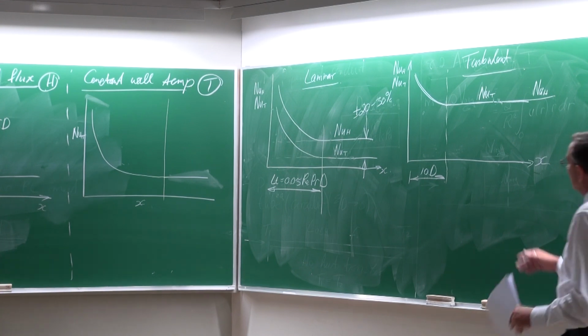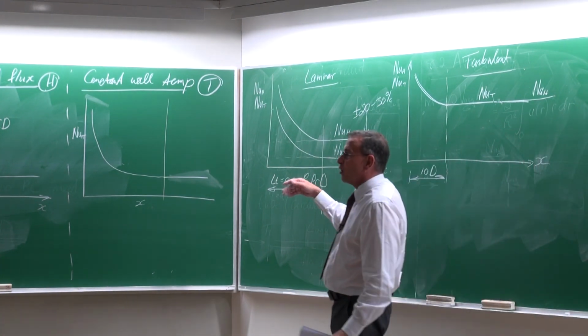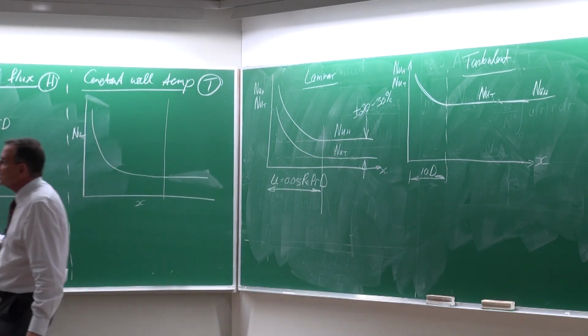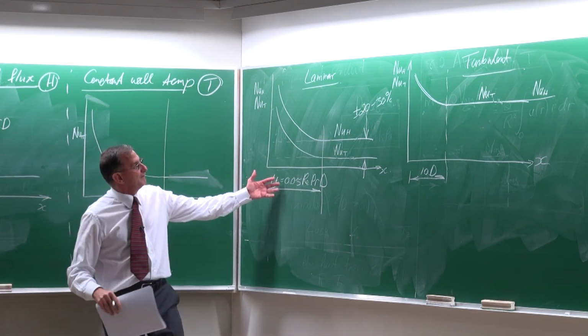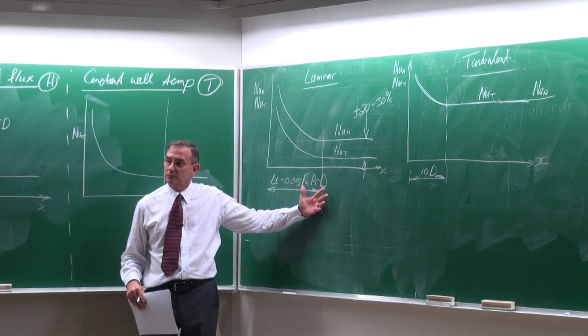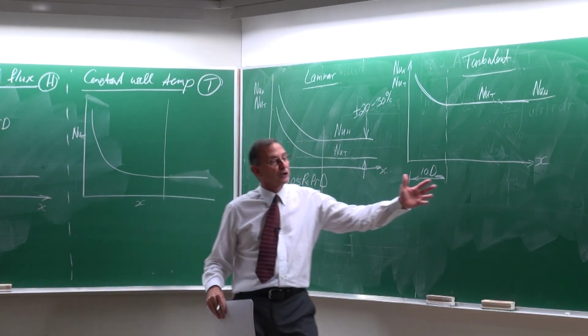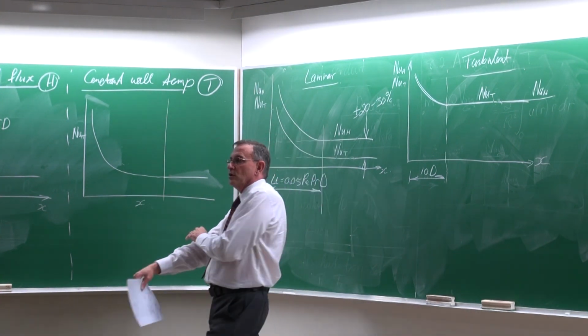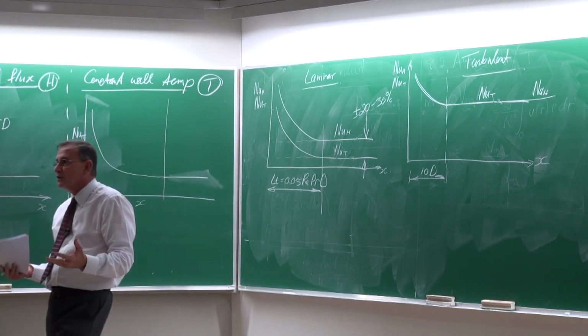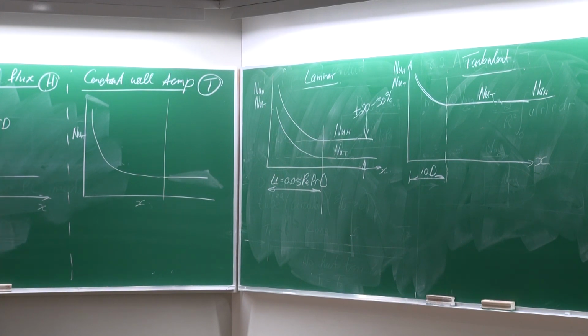The bottom line is that the type of heating and or cooling condition that is going to be used, constant heat flux or a constant wall temperature, has a significant effect in the laminar flow regime. Okay, but not in the turbulent flow regime. So normally, if you calculate the Reynolds number and it's turbulent, then you can say for yourself, yeah, I've got some less work to do. I don't have that much to calculate. It's easier.